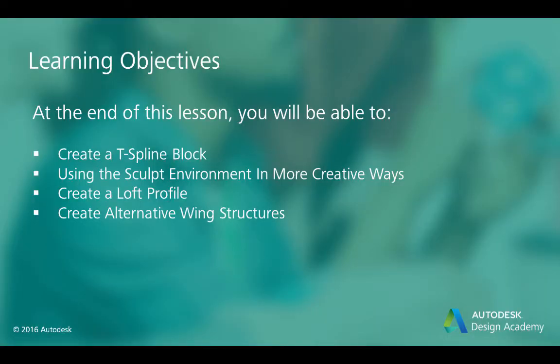Tip set 1. Let's talk about a few alternative approaches. In this video, you will learn a few alternative ways of modeling an f1inSchools car in Autodesk Fusion 360. After completing this, you will have learned various different methods for modeling a car. In this activity, you will learn how to do the following in Fusion 360. Create a T-spline block, use the sculpt environment in more creative ways, create a loft profile, create alternative wing structures. Step 1. Create a T-spline block.